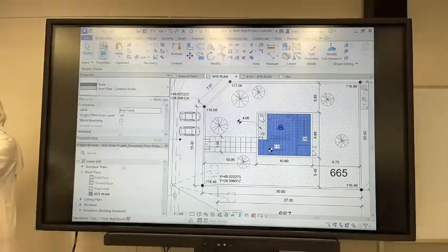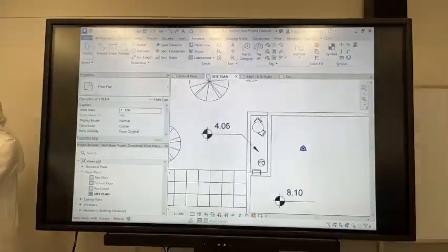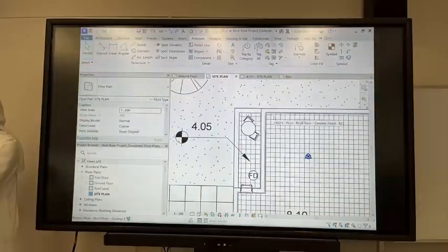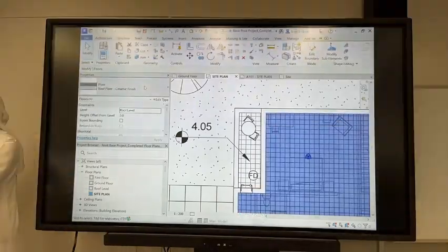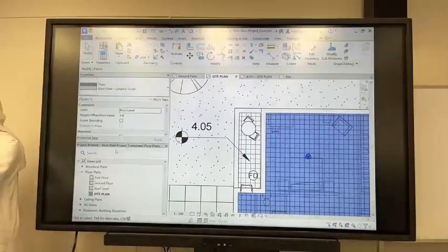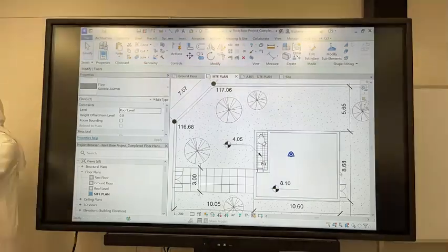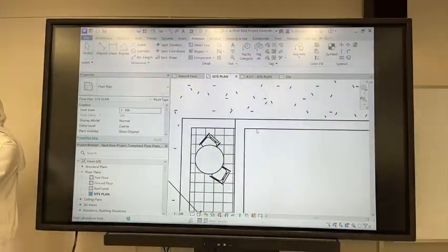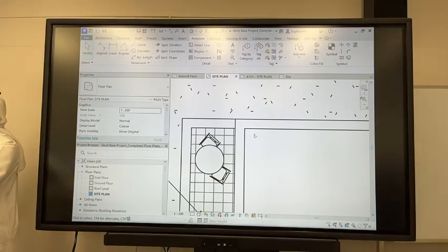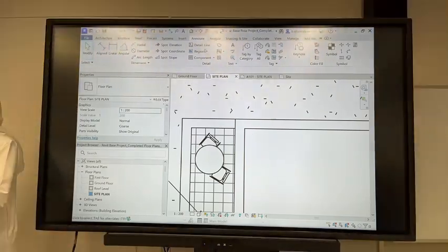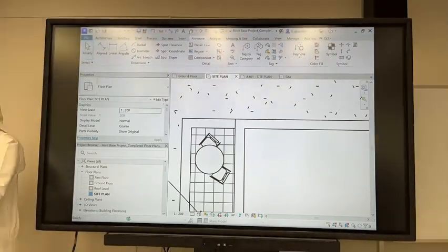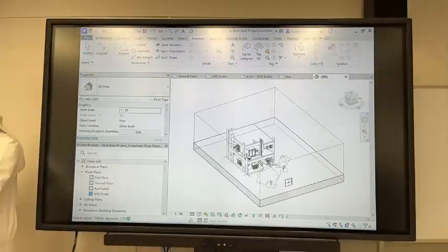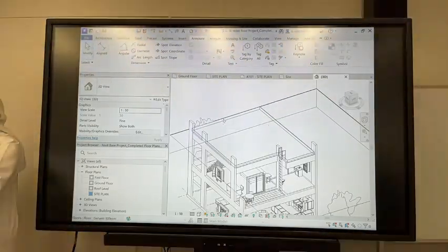Which slab? The top floor slab and the balcony, so you're going to do it twice. So one for the top floor slab right now, by double-checking generic 300, right? You can eventually go to the edge if you can't find it. You could go to 3D view and change it there anyway. You can go to the roof. If you're not able to catch it, it's fine. You can get it from another view.